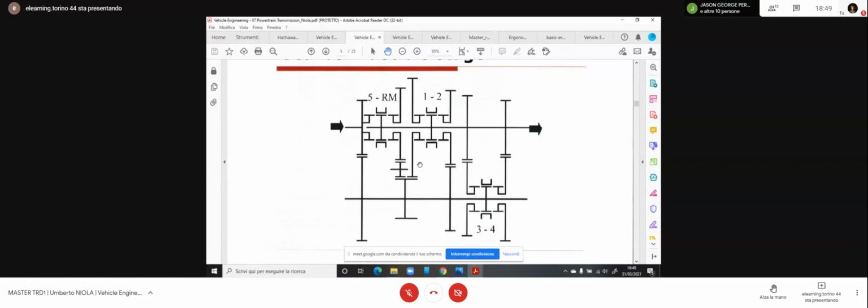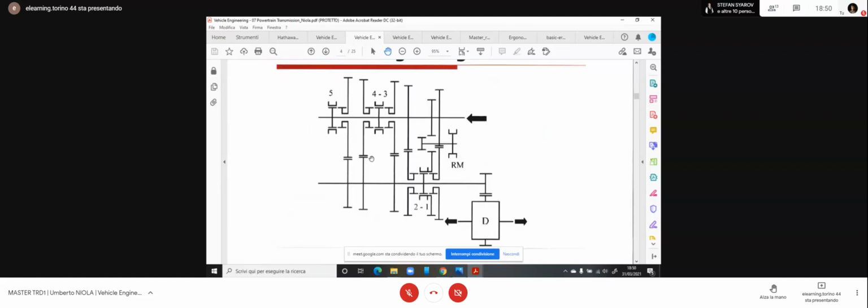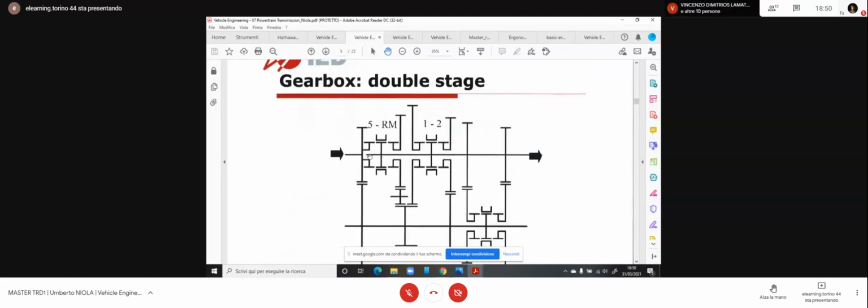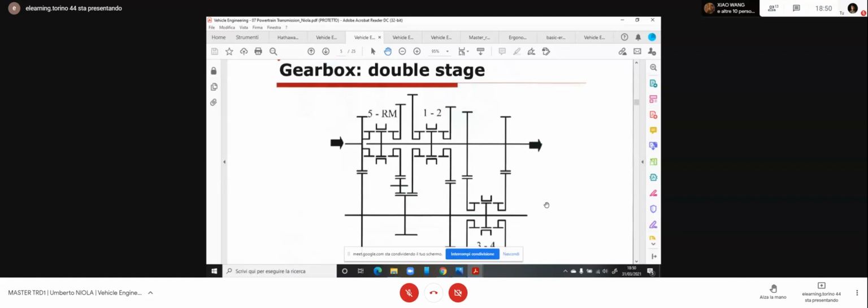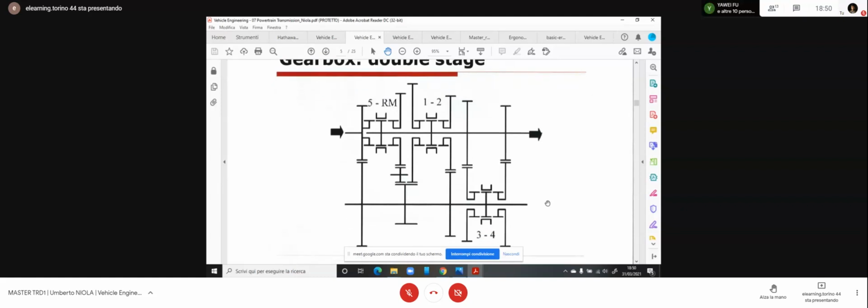This is also used on some motorcycles, and it is easy to identify because you always can see the output sprocket. This is directly in line with the clutch. This is not back to the clutch, which is the first kind of two shaft organization. If you have this kind of direct line, like maybe Harley Davidson, they use this kind of gearbox. Okay?